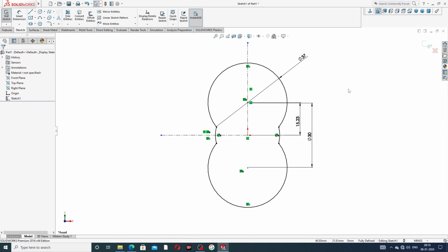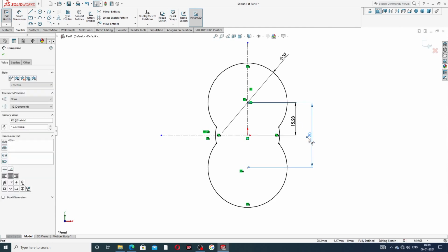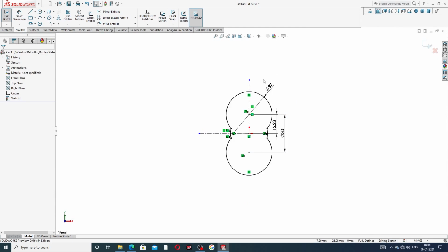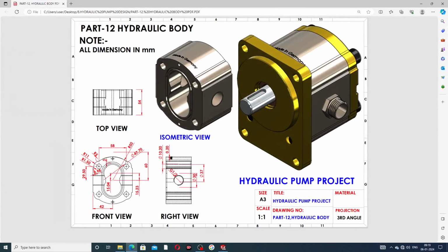This body is drawn here, and it is perfect and correct. All distances, all geometry, and all dimensions are perfect. Next, use this center. Next, draw the inner side here. And next, use this upper side line, and use a center point arc. This radius is 15 millimeter.